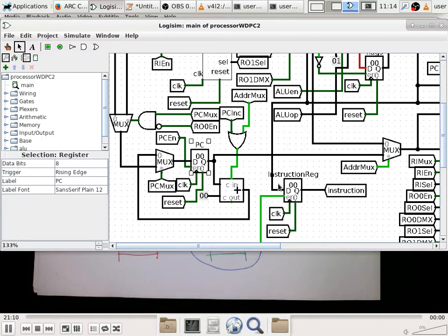It has to be pretty much a fixed place or pre-programmed space. Yep. And this is also why in most processors they have a, quote-unquote, software interrupt instruction, because that instruction is just a software way of triggering exactly the same mechanism as if a hardware interrupt just happened.